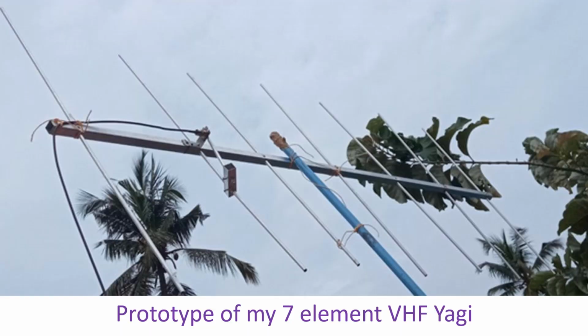The gain of a Yagi-Uda antenna increases as the number of elements are increased. This will also increase its front-to-back ratio. An indication of front-to-back ratio can be obtained by changing the direction of a VHF Yagi-Uda antenna and checking the access to local repeaters.